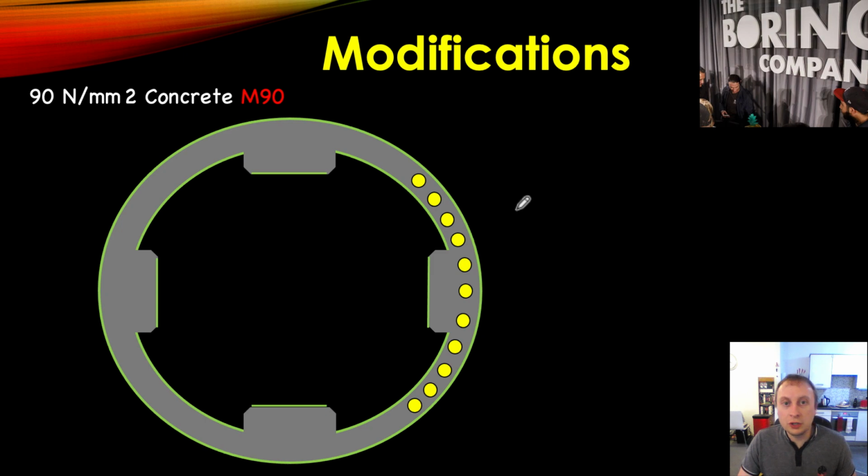Now, what I want to do is I want to increase the thrust potential of the machine quite dramatically, but I want to do that in a way that's not going to absolutely destroy the tunnel segments that I've got lined up behind me. The main way I've done that is I've increased the surface area in these four points here. That allows me then to add 2 much larger thrust cylinders here. Now, these thrust cylinders are quite a bit larger than our other 8 here, around 160 to 180% more power per jack, maybe slightly more than that, and they can work in this area here.